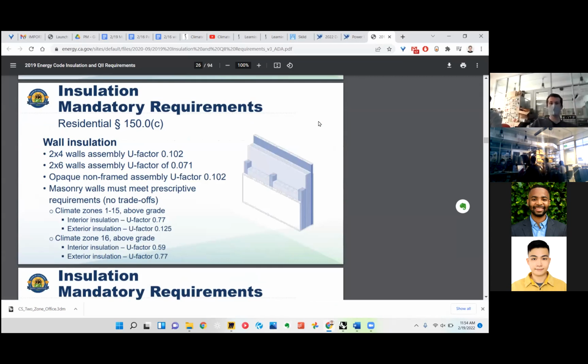We're trying to make it more sensible instead of still having very fake values. Yeah, these are going to be the code minimum requirements. We just put those for the sake of giving more realistic figures, because in the previous project summary I could see some values that are unrealistic, like the walls with 11. Is it 11? Which is drastic for a U-factor.